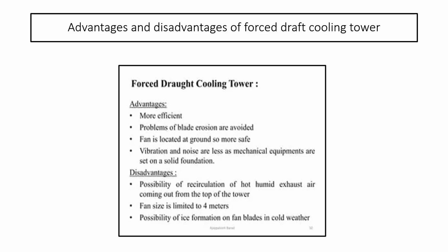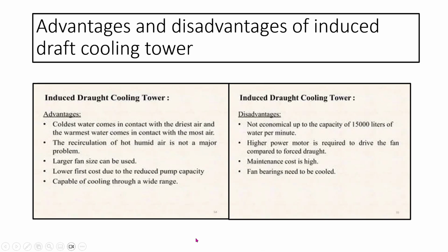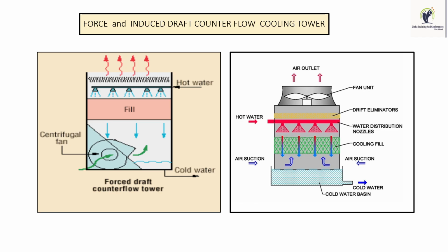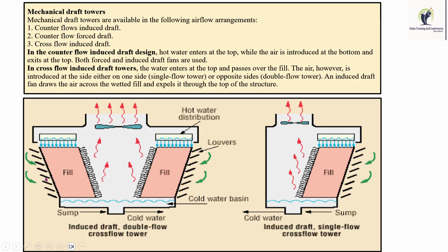And then next is induced draft, its advantages and disadvantages. What is the advantage of induced draft? The coldest water comes in contact with the driest air, and the warmest water comes in contact with the moist air. If you see the picture, this one is the coldest, dry air coming in contact with the water which is coming down.